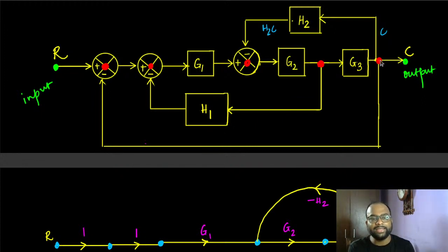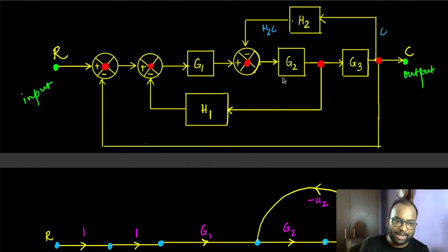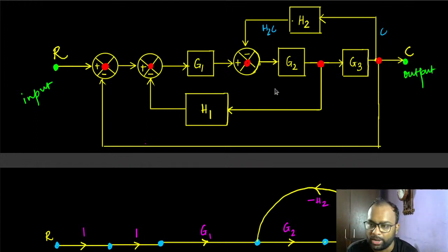So the idea is that it is drawing a minimal amount of current and only sensing the voltage or signal, and it could be buffered with op-amps. There could be buffering amplifiers that are actually buffering the signal. So even if it draws some current, it does not matter to the circuit. The signal does not change. So there are buffers everywhere. Buffers are capable of delivering the additional current required by the devices without altering the voltage. So assume that there are buffers at all the tapping points.